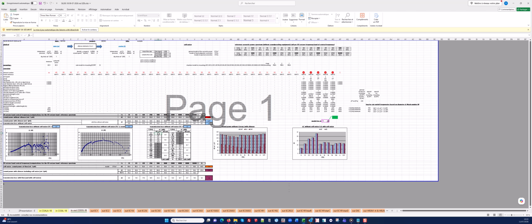1/3 octave band and 1 octave band are computed, as well as an overall A-weighted value with respect to the reference spectrum entered. LW0 is the unsilenced sound power level.